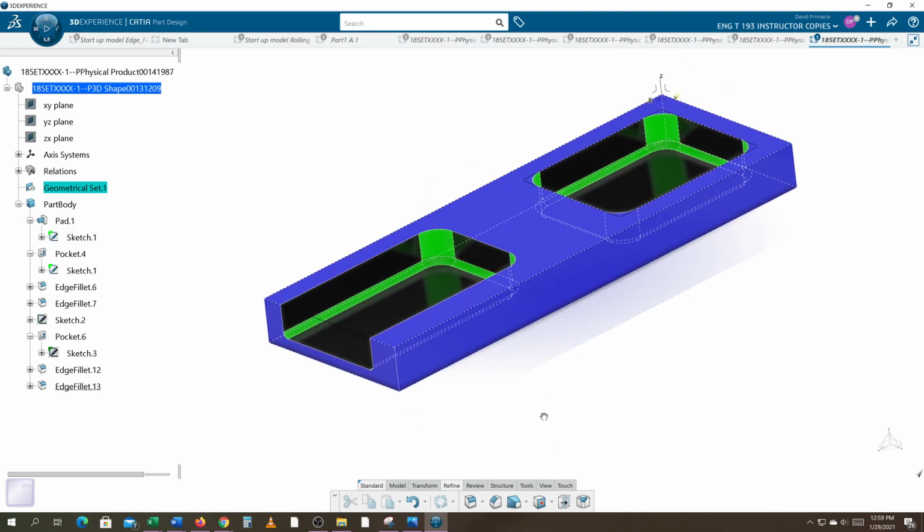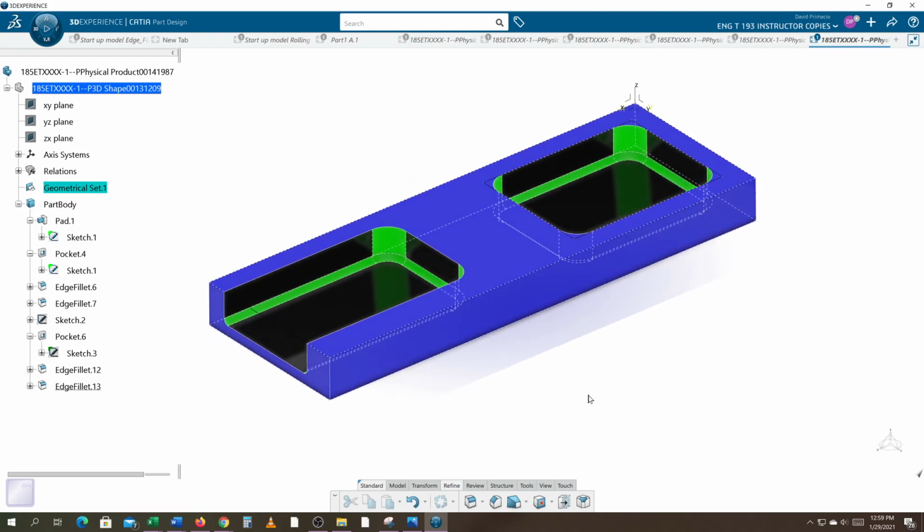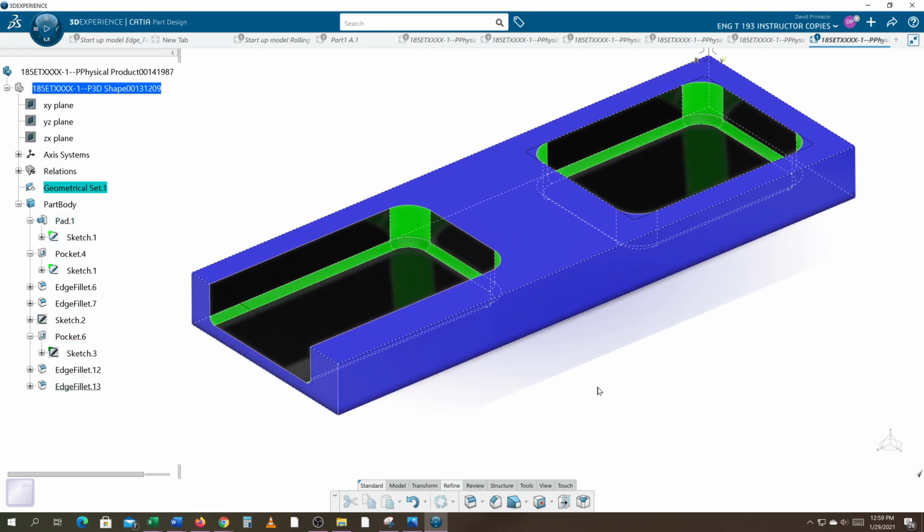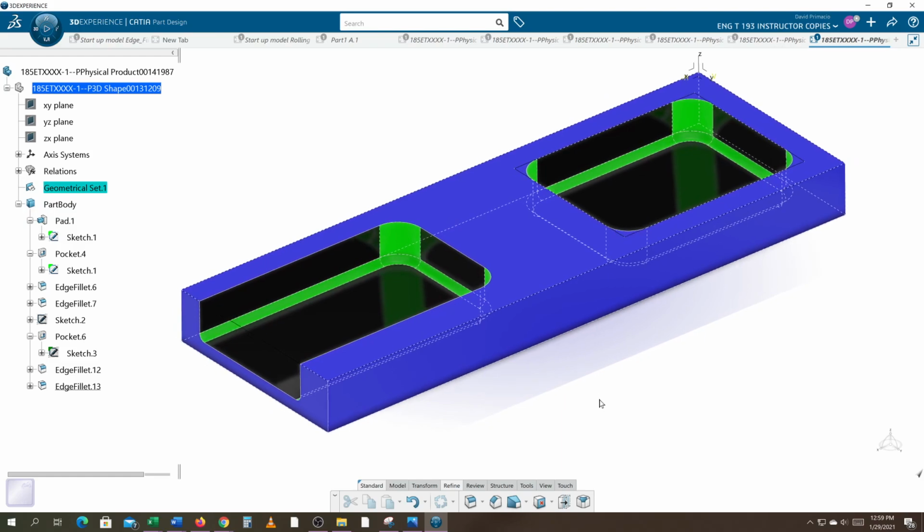All right, so there is a technique you can use to create the pockets. This would be a pocket, this would be a hog out, because it's not a pocket anymore because it's broken through the wall. This is my wall thickness over here. My web thickness is the distance between the pockets. Okay, so in this instance, it was better to create an additional sketch than to have everything done in one sketch. So that's how you would have to fix that if you did do everything in a single sketch. I do have another technique that's very common that I'm going to show you next.